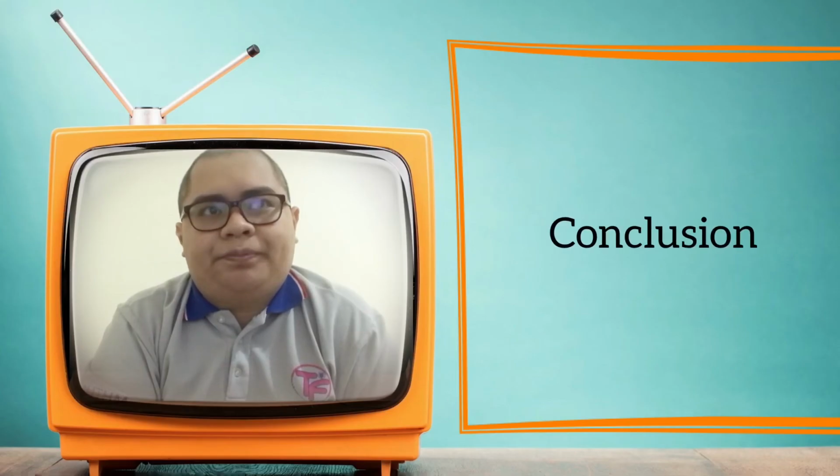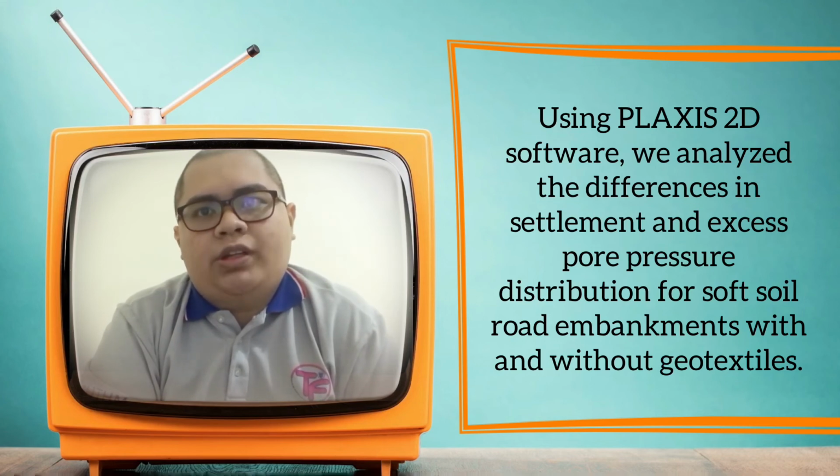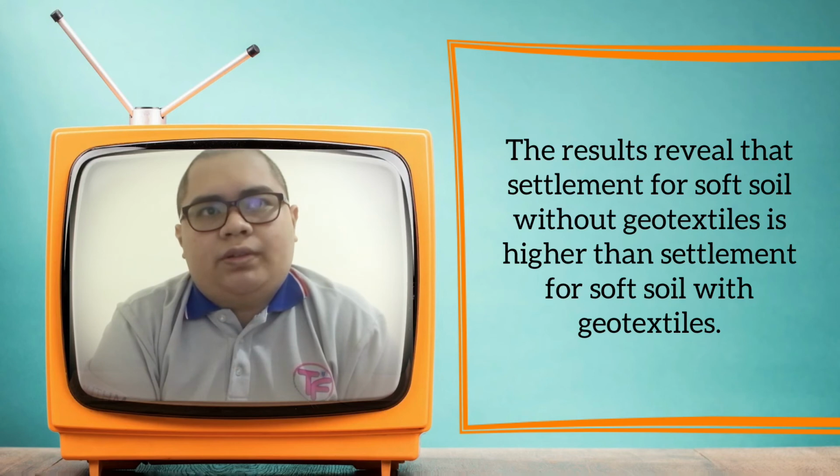The conclusion. By using Plaxis study software, we have analyzed the difference in settlement and excess pore pressure distribution for soft soil road embankment with and without geotextile. The result revealed that the settlement for soft soil without geotextile is higher compared to soft soil with geotextile.